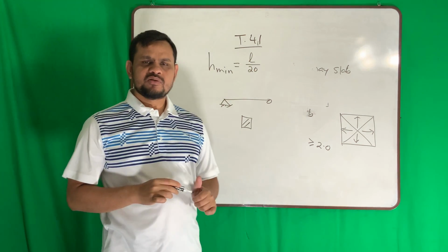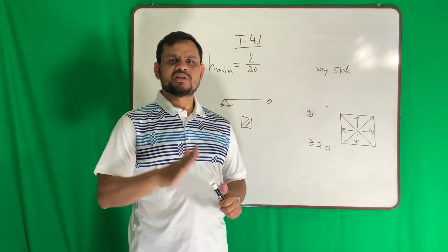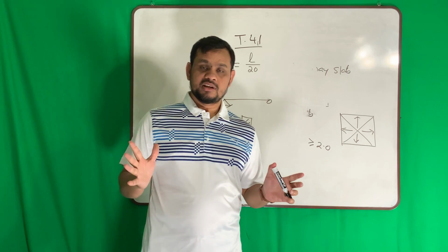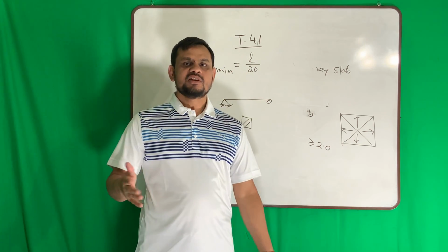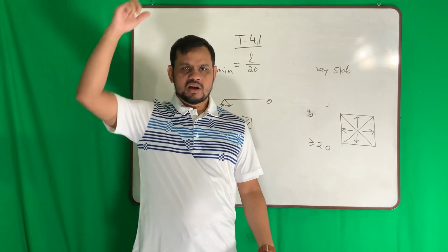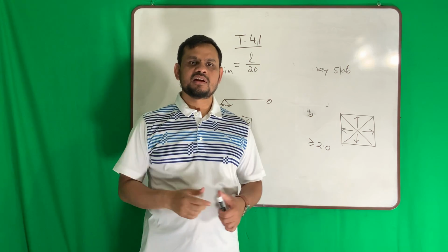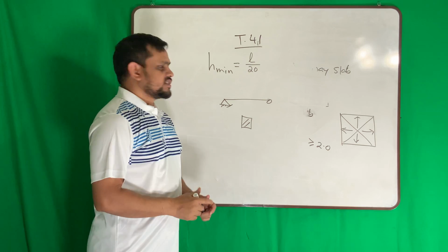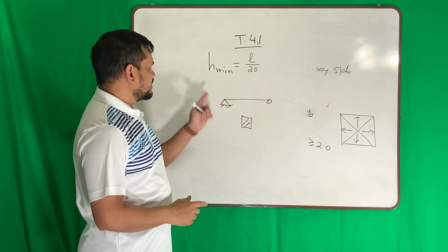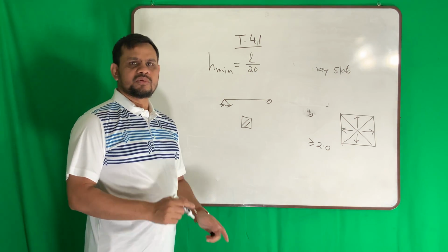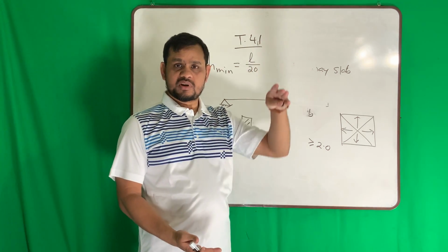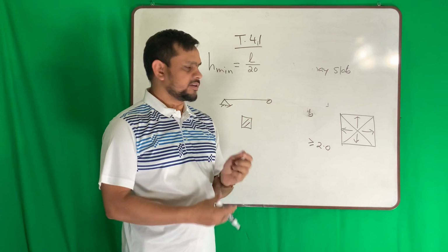Now again, this requirement is just a vibration requirement. It is not structural. That means if you do not provide it, your slab will not fail. It will just vibrate. When somebody upstairs walks, you will hear the vibration or the noises. Yes, this is a concern issue for slab. For beam, typically the thickness or depth is so high that we do not need to be concerned about it.